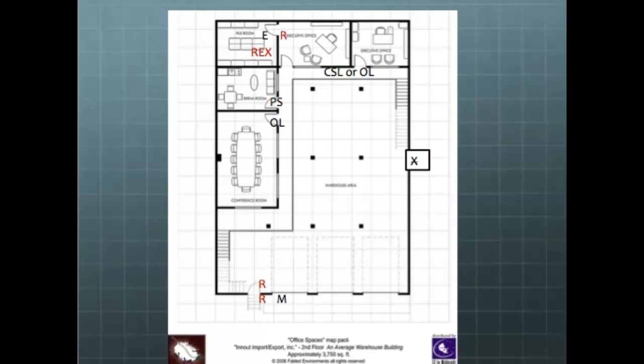Now we went over to the file room. Do you remember the instructions on the file room is you needed to know who went in, but not necessarily who went out. On this one, I put a reader on the outside, and I put a REX on the inside. Now, the size of the room, the REX device, you have to be careful with. You'd have to really tune it in. Otherwise, you'd be setting it off when you're on the far side of the room.